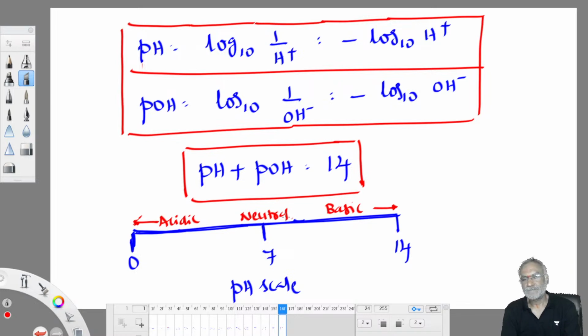Third important thing is, why pH is measured is, I told you, the water treatment is pH sensitive. Second is, quickly we can find out whether water is acidic or basic with the help of pH. The third important thing is, the cost of chemicals used in water treatment also depends on pH. At one particular pH, while treating that water, it requires very less amount of chemicals. At some other pH, it requires huge amount of chemicals. So cost of treatment also depends on pH.